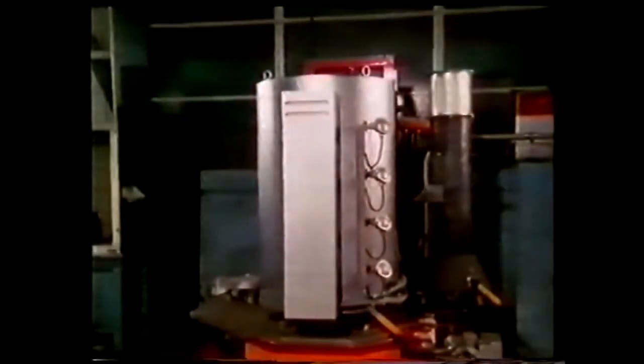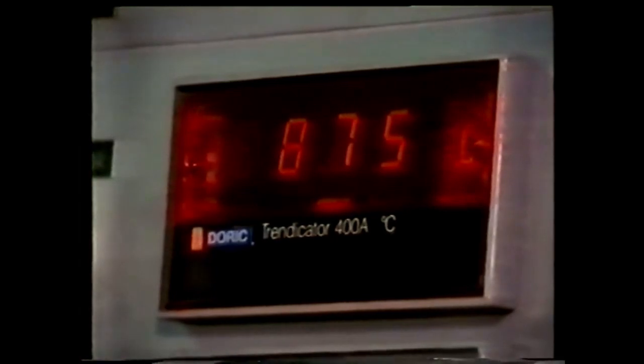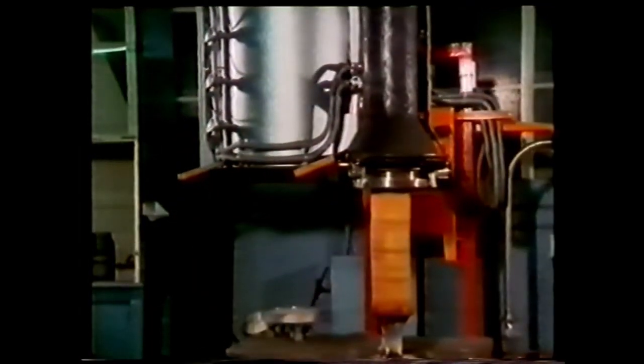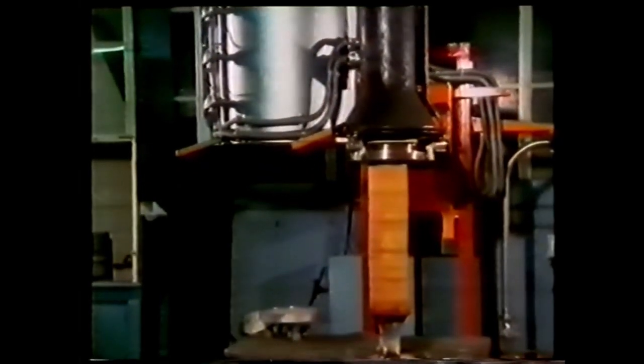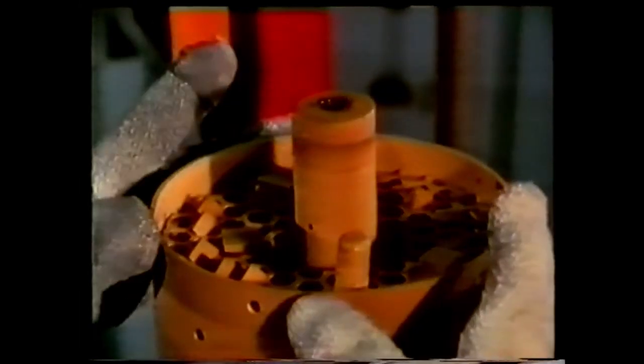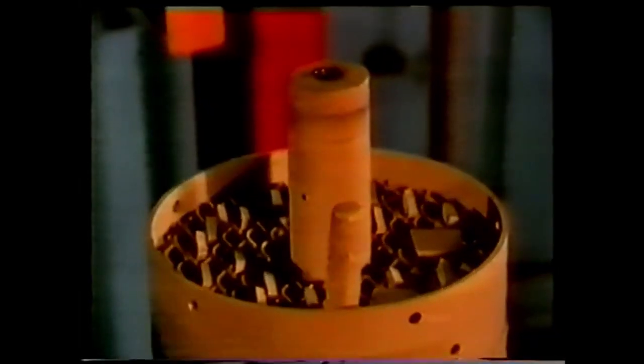The inserts are produced in a wide range of shapes and sizes. After checking the final geometry, the insert undergoes facial and peripheral grinding. Although the inserts can be used at this stage, most undergo a coating process. They're placed for about 9 hours in a vacuum chamber at temperatures exceeding 1,000 degrees centigrade. During this period, a very thin coat of titanium nitride, or carbide, about 6 or 7 microns, is added to the surface. This coating improves the cutting properties of the material and extends the life of the tool.